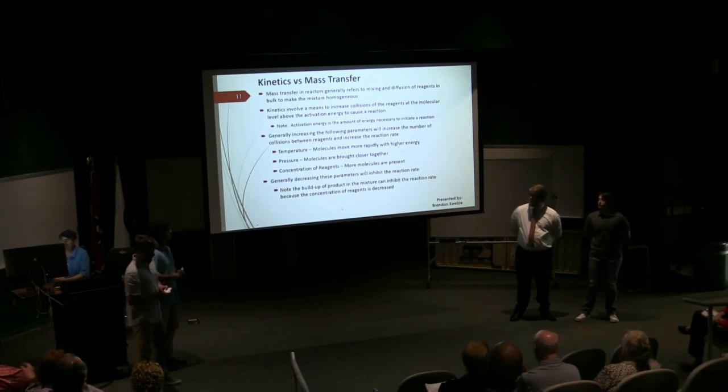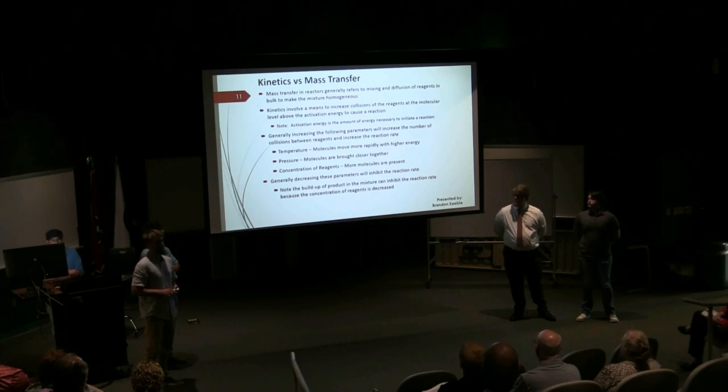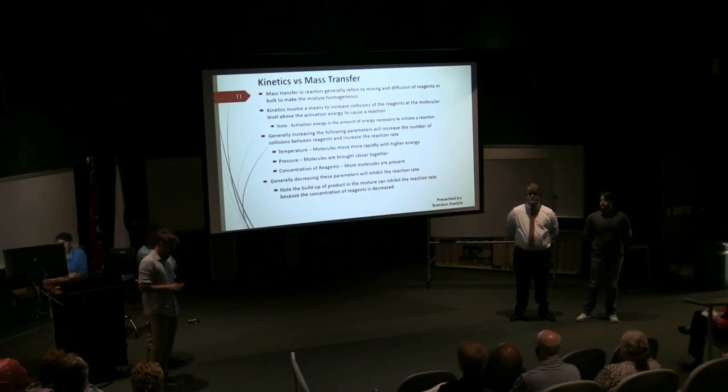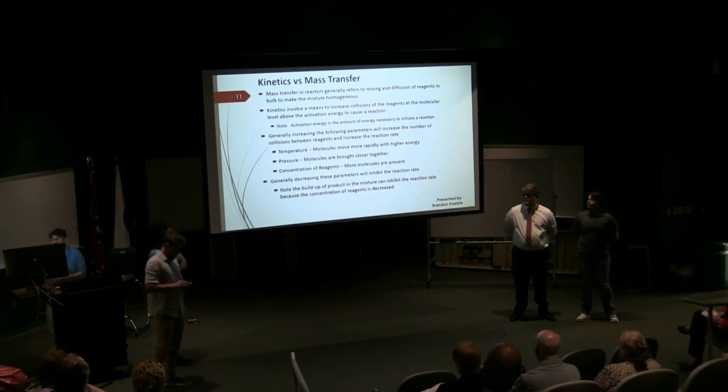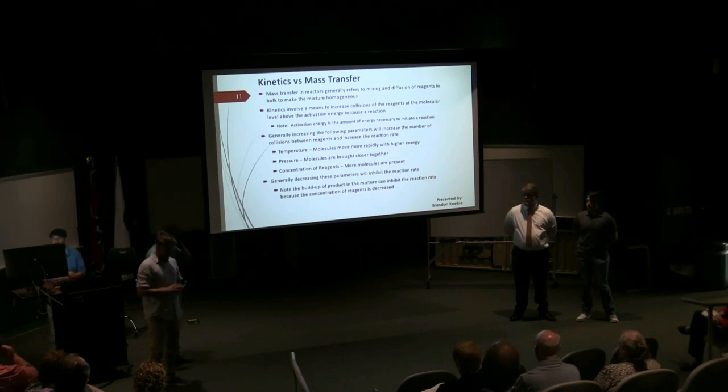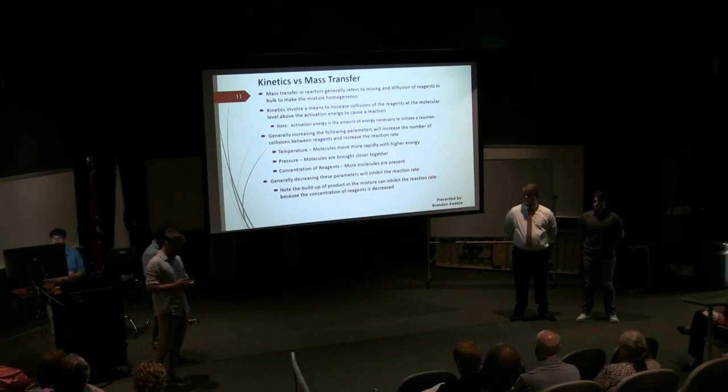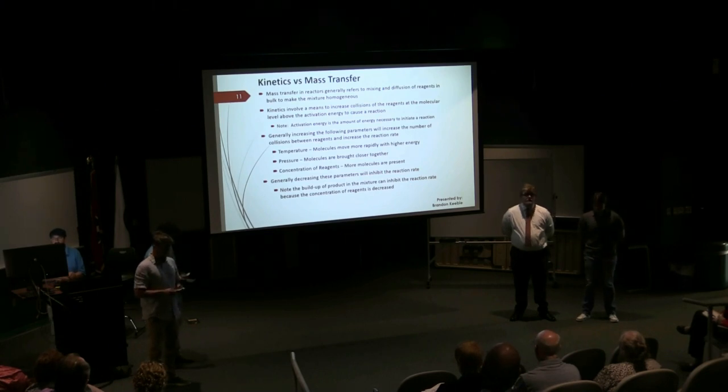In discussing reactors, it's important to discuss the difference between mass transfer and kinetics. Mass transfer ensures uniform reagent mixing throughout the reaction. Reaction kinetics are driven by molecular collisions and influenced by temperature, pressure, and concentration. And product buildup reduces reactant concentration and slows the reaction.